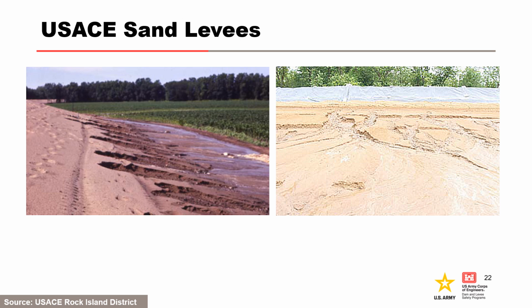These figures show sloughing due to seepage through sand levees with steep slopes. Sand levees without a waterside impervious layer reach steady-state conditions rapidly and are prone to through seepage. Seepage exiting on the landside slope would result in high seepage forces, decreasing the stability of the slope. Through seepage has been successfully mitigated for these levees by using sufficiently wide levee sections with flat slopes, although these slopes do require maintenance during high water events. For example, there are many miles of sand levees in the Mississippi River Valley with 5-to-1 landside slopes and 4-to-1 waterside slopes.